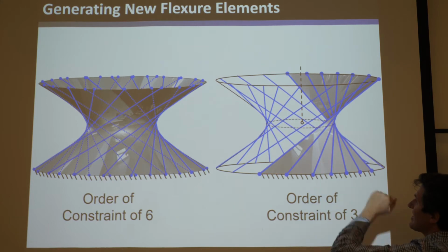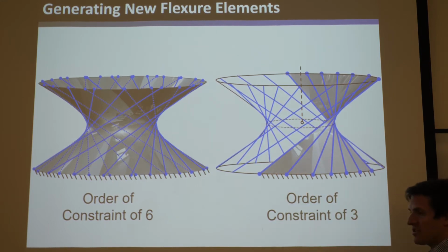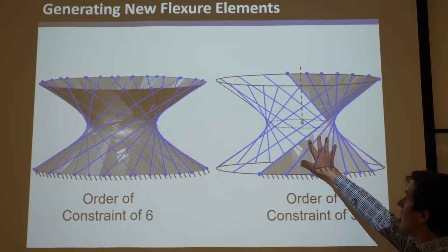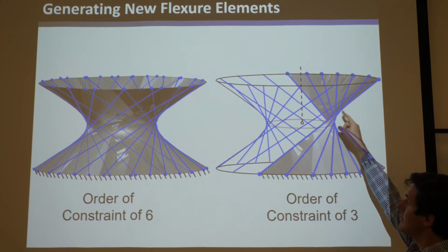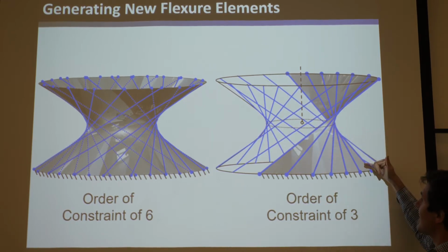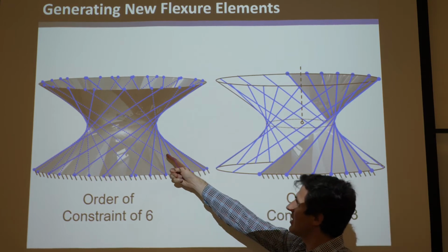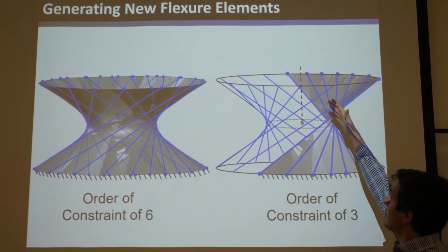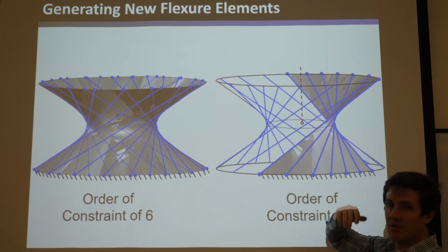And that's why this guy, the only blue lines that satisfy the 2 conditions of a parallel element are these ones from this set. They connect the 2 bodies, they pass entirely through its geometry, and they can fill the whole thing still, but there's not a single blue line that can satisfy that condition for this sector. If we tried to draw any of these other blue lines, you could draw them so they connect the 2 rigid bodies, but it would exit this geometry and violate one of the conditions.